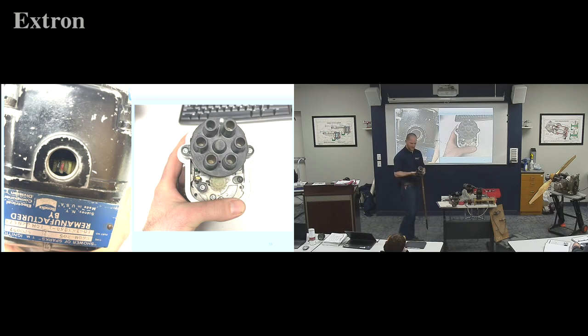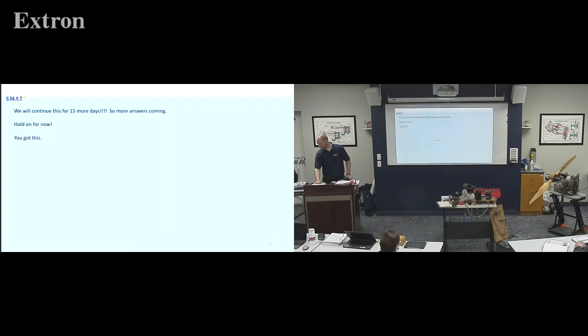They have a window opposite the magnet, so it'd be under that screw, or on this one, opposite the magnet, so under this screw. That's where you're going to look in and see the window. So the Bendix have the window, and you're going to line the paint and the tooth up. I recommend looking at these as the class goes further. Where our Slick has the pin that you're going to pin in there.